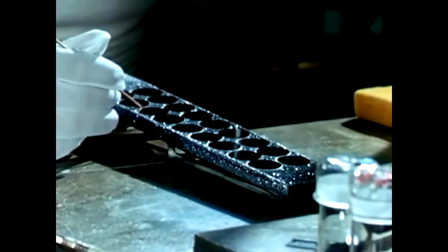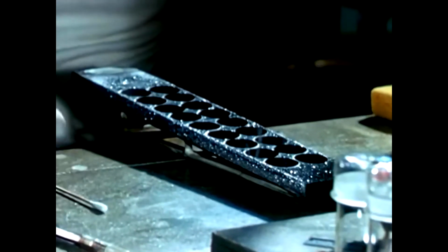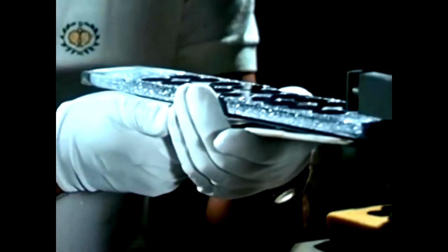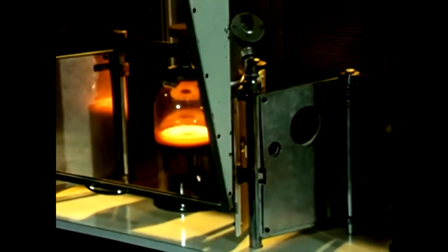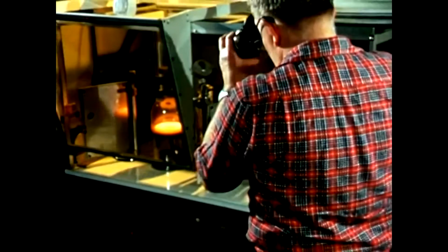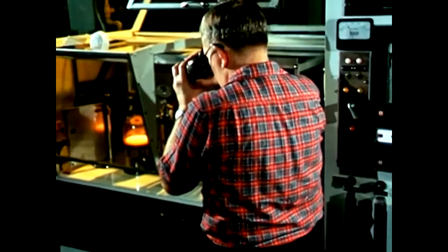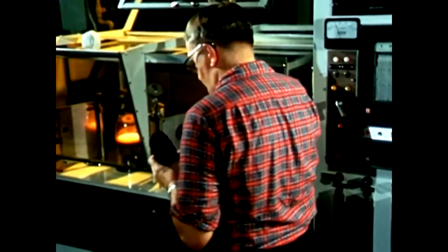This single silicon crystal will be trimmed, then sliced and diced. These slices have been cleaned in a liquid by means of ultrasonic energy. A special technique, called epitaxial deposition, involves the growing of molecular layers in an oven to extend the originally grown crystal structure of the silicon slices. Control of temperature is critical. It must be uniform across the slices.